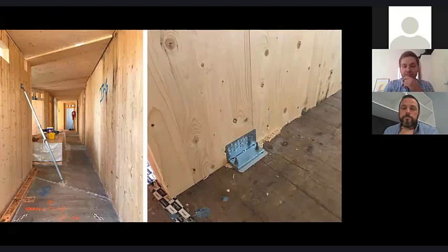Like Rob mentioned, you have to really design for the loads, of course. With any timber, a larger quantity of smaller fixings is always best for ductility, but it's not always necessary. So designing to your actual design loads is really crucial.